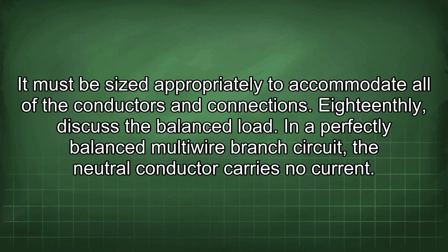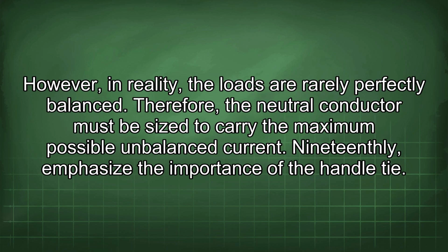18th, discuss the balanced load. In a perfectly balanced multi-wire branch circuit, the neutral conductor carries no current. However, in reality, the loads are rarely perfectly balanced. Therefore, the neutral conductor must be sized to carry the maximum possible unbalanced current.